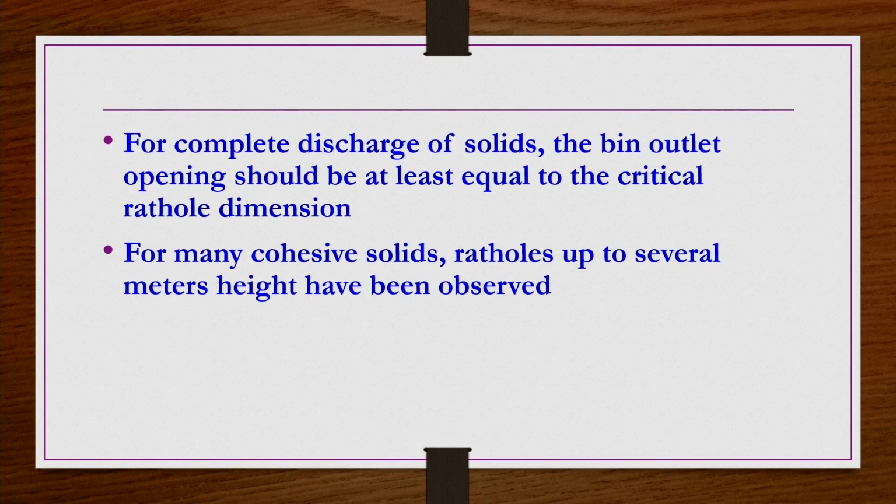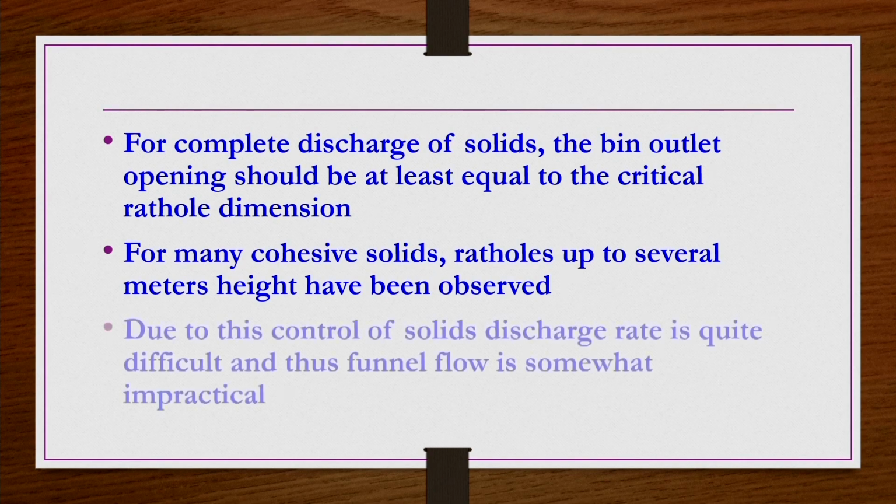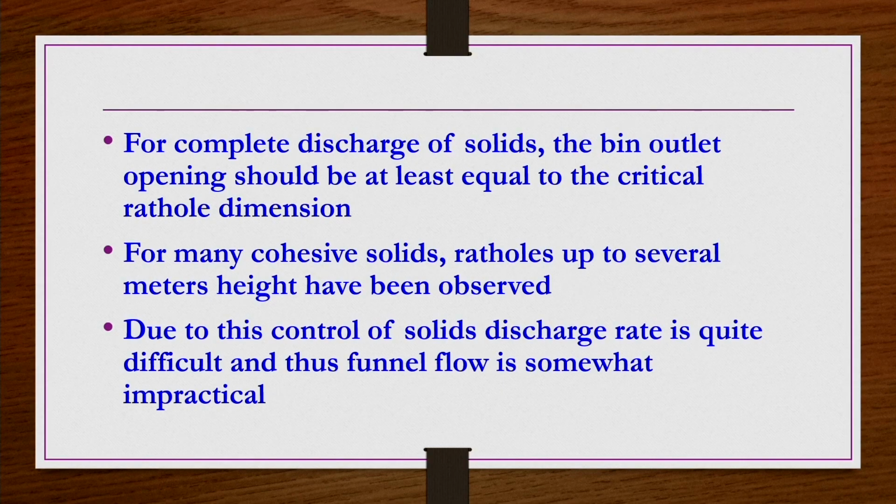For many cohesive solids, rat holes up to several meters in height have been observed experimentally. Because of rat hole formation and the dead storage, where material gets into the bin first but leaves last, control of the solids discharge rate is quite difficult, and for this reason funnel flow is found to be somewhat impractical.